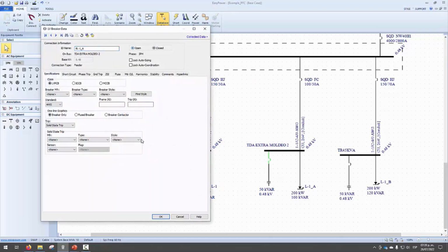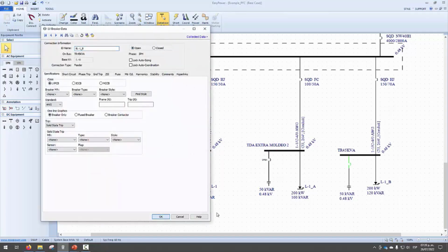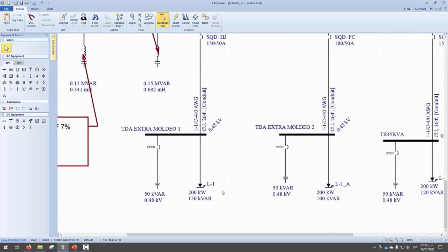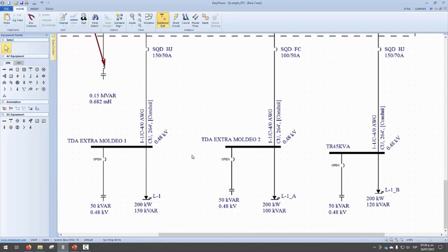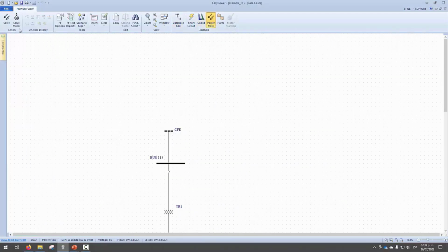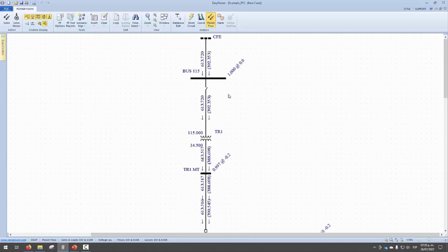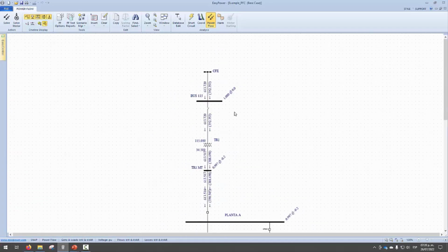So let's say that I did a power quality study with a handheld analyzer on my facility, and what I found was that I have these three loads as modeled here. Now, when I run the power flow model, I find that I need 392 kVARs at the top of the system, so the utility can see a unity power factor, right? Which would be ideal.